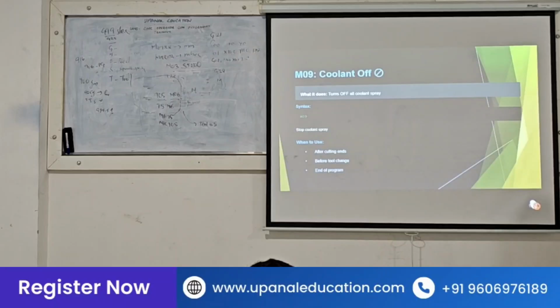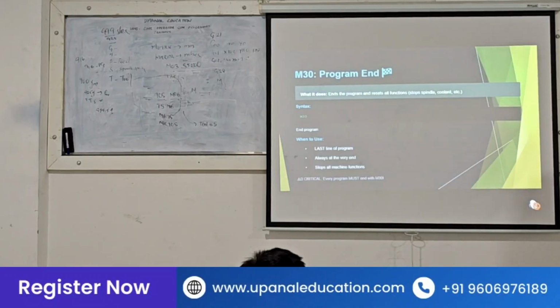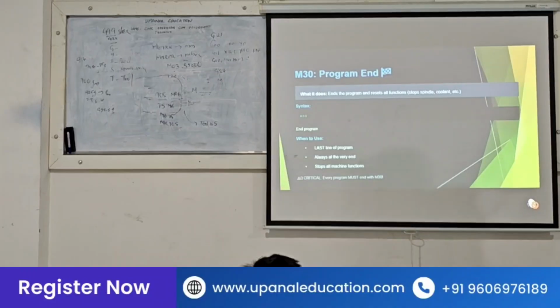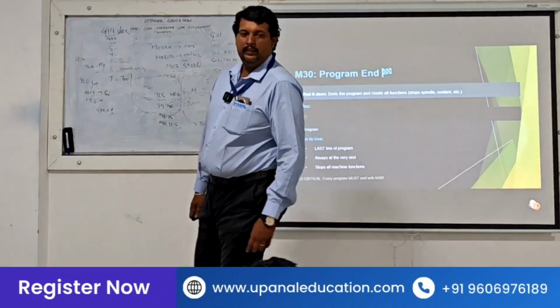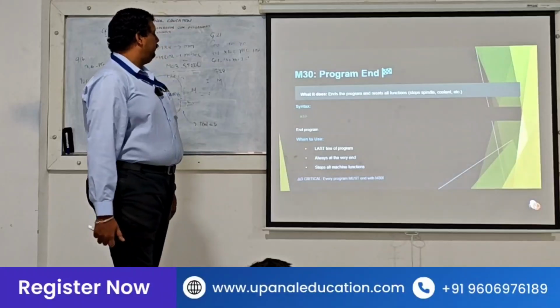Then after the work is complete, we are telling the machine, okay, the program is complete. For that we use the code M30. M30 means program end.